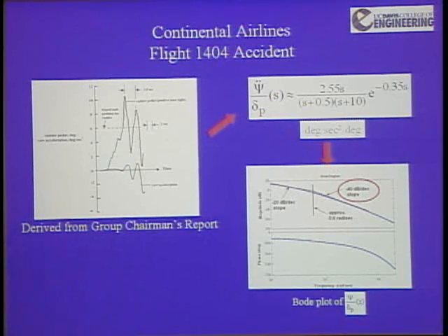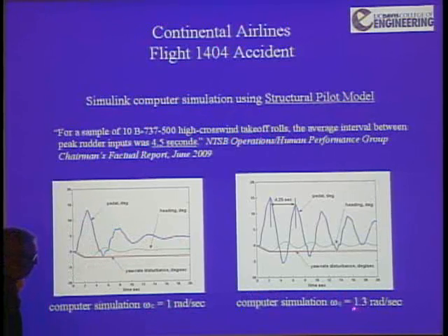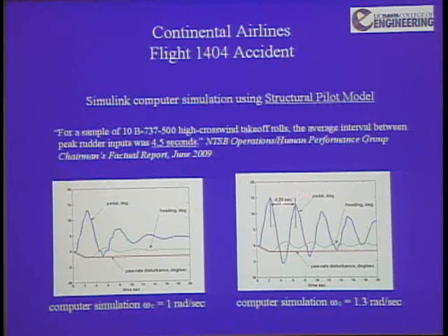Bad handling qualities. Okay? So what I did is I set up my pilot model, and I played around with the crossover frequency of the gain. And I said, if the gain gives me a crossover frequency of 1 radian per second, I get some oscillations. If I bump it up just to 1.3, I really start getting some oscillations in heading. And what made my day was that the oscillation frequency I was getting was 4.25 radians per second.